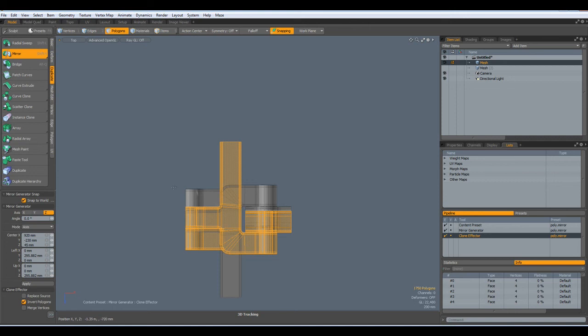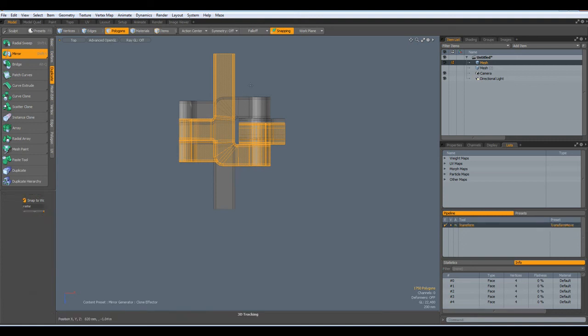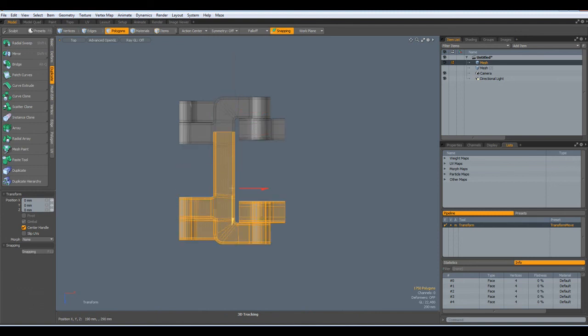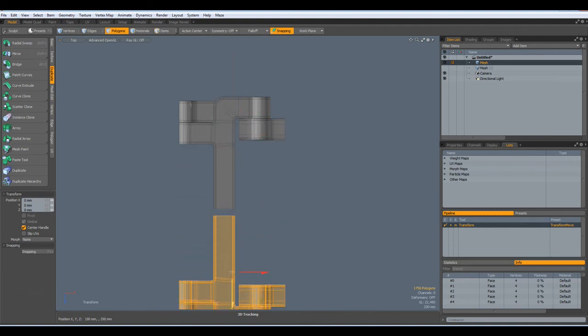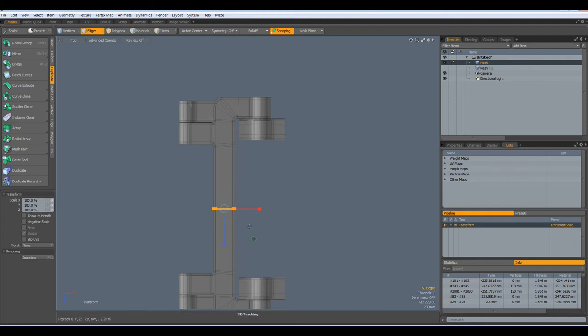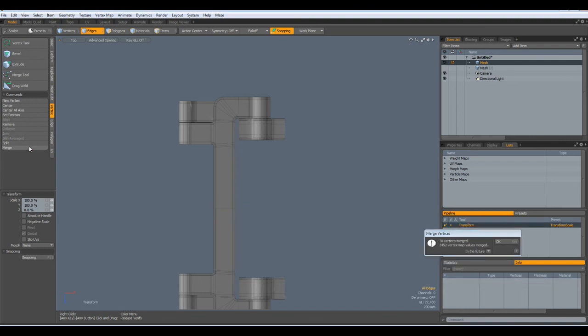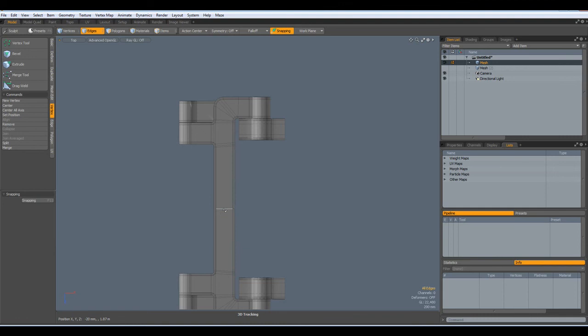And you see now the advantage of highlighting one part when you are completely off any axis, because the highlighted ones remain, and we can now put this one to the right position, which is about here. So select this, vertex merge automatic, 30 merged, good, we don't need this.